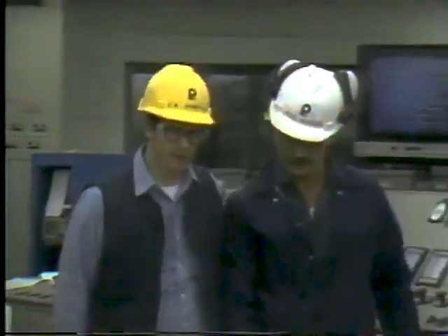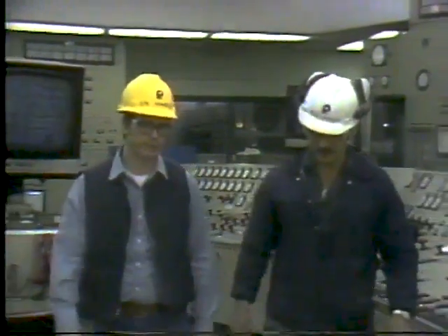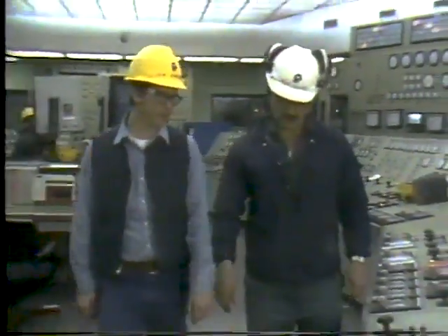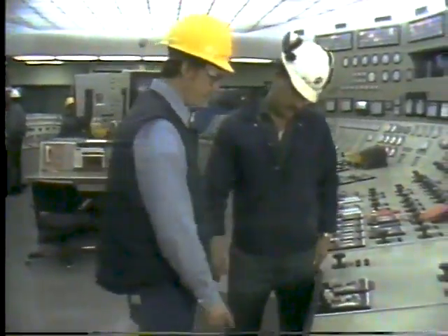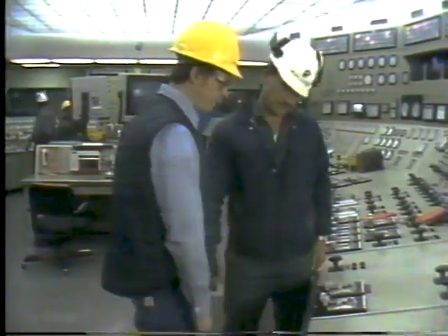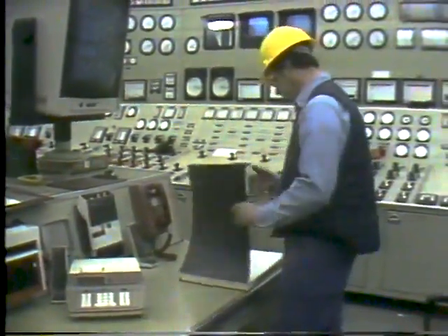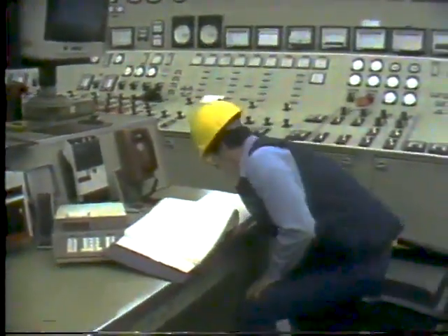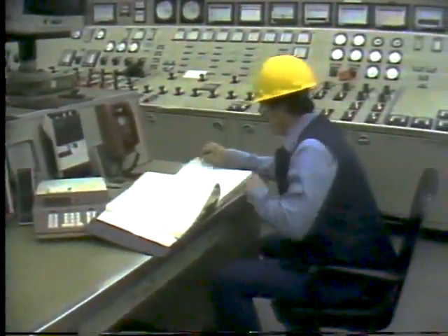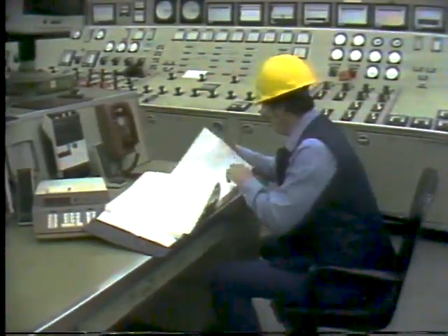Let's see how the technician prepared to tune the system. First, he discussed the system with both operating and engineering personnel. Then he studied the P&IDs, control logic diagrams, the appropriate service manuals, and the calibration records. After studying the system and talking to the right people, he had learned what he needed to know to tune it.